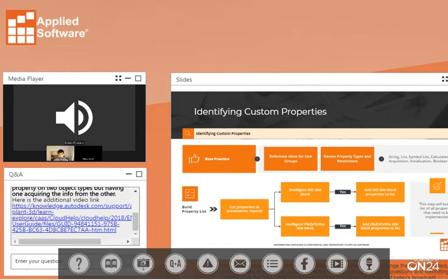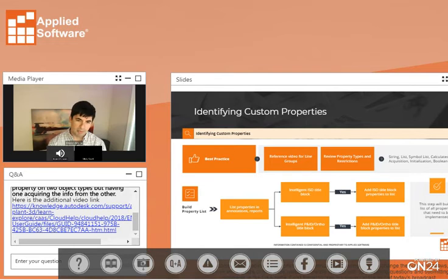And then also reviewing your property types and restrictions. That kind of adds on to the different restrictions here. So your different property types: string, list, symbol list, calculated, acquisition, and Boolean. These are all options when you're picking a property that you have to create and configure. So for example, status would be an example of a list. You might have existing, new, or demolition.